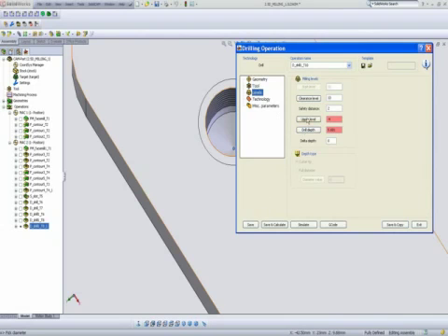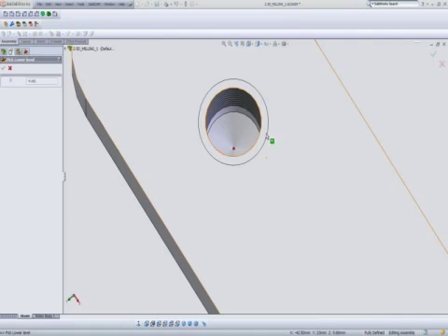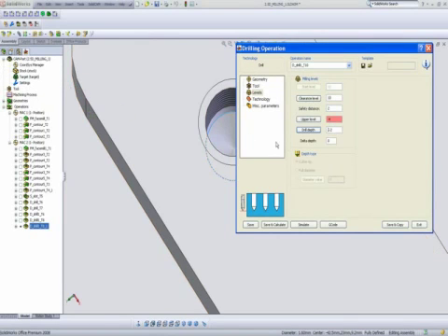My levels, my upper level will stay the same. My drill depth, however, I'm going to change it to go down only up until that area over there. If I want in my delta depth, I can say 0.2, having going 0.2 millimeters above that point over there.